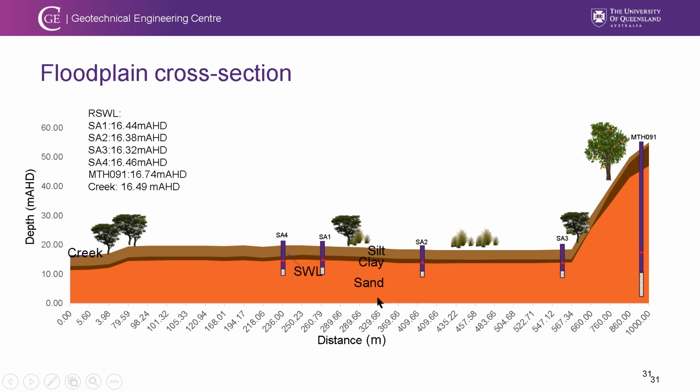Once we have the well constructed, what we find is that the water level just increases from 5 meters below the surface to 2.8 meters below the surface, which is the indication that the groundwater table is a confined water table.